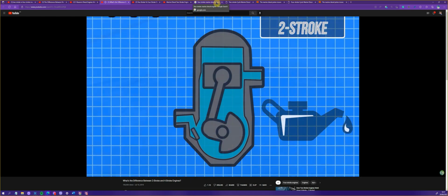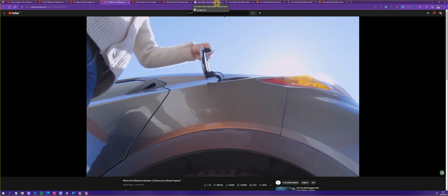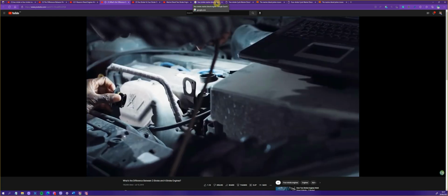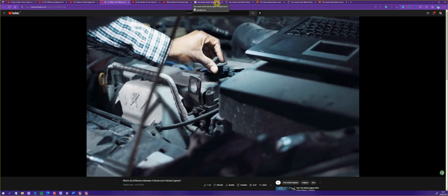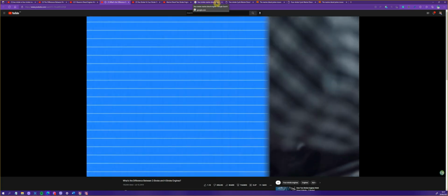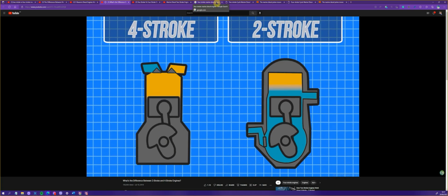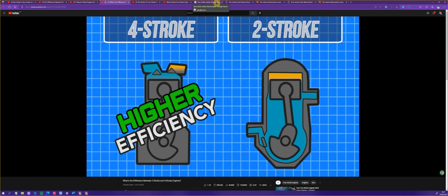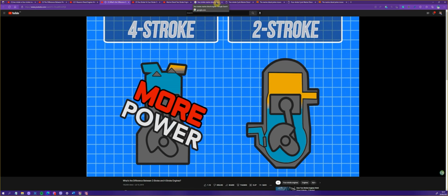A four-cycle engine uses normal gasoline like your car, which also happens to be a four-stroke engine, and the oil is injected from a separate reservoir. This eases the burden of fueling the engine up, but of course there's always the possibility that the fuel pump will break. All things considered, even with the drawbacks of the four-stroke, four-cycle engines maintain higher efficiency over two-strokes and can produce more power than comparable two-stroke engines.